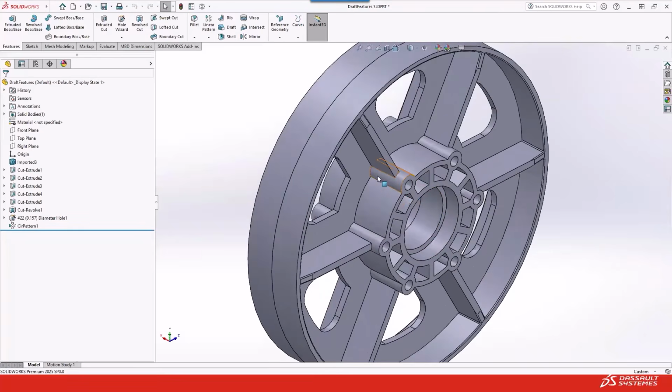So right now, these are nice and straight. Same diameter here as up here. But oftentimes you need to add taper or draft, as they call it in Solidworks, if you're extracting something from a mold. If you're trying to pull it out of a mold, it's easier if it angles in as it goes away from the direction of pull.